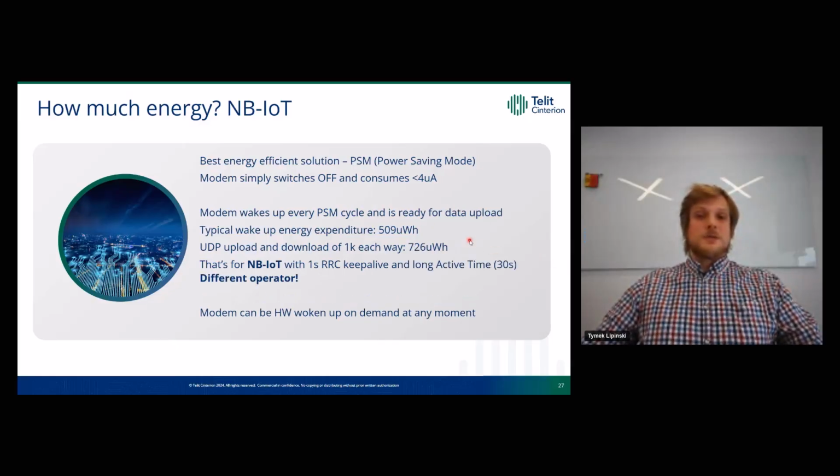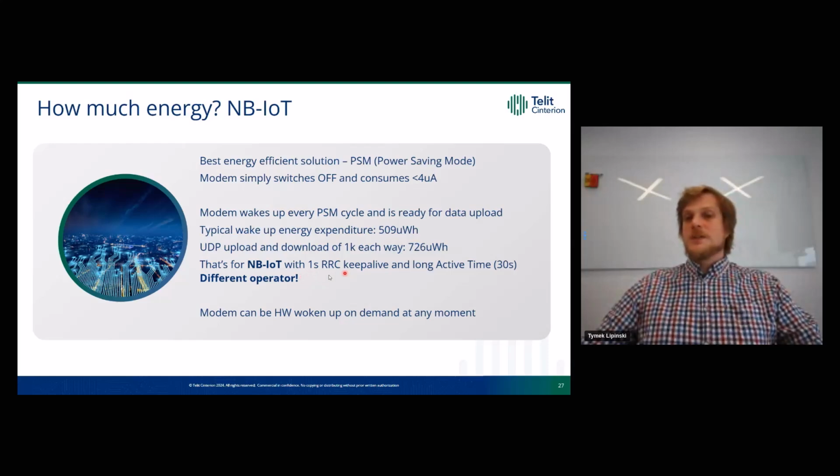Let's use a different operator for the same example, which keeps the RRC only active for 1 second after the last data transfer. Look, it dropped to 509 just to wake up and go back to sleep, and upload and download jumped down to 726 microwatt hours. That's really nice. It could be even lower because we were using a very long active time for the PSM timer. It was 30 seconds, but we were using a different operator.